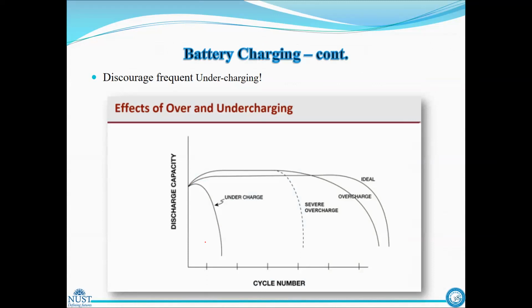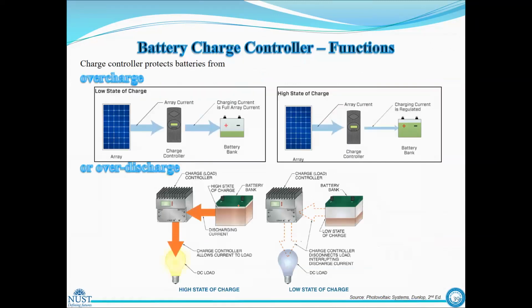You can see here, we should discourage frequent undercharging. Why? Because the overcharging is detrimental. Again, the severe overcharge can further decrease the cycles of the battery life, but undercharging is really severe or damaging to the battery life particularly.